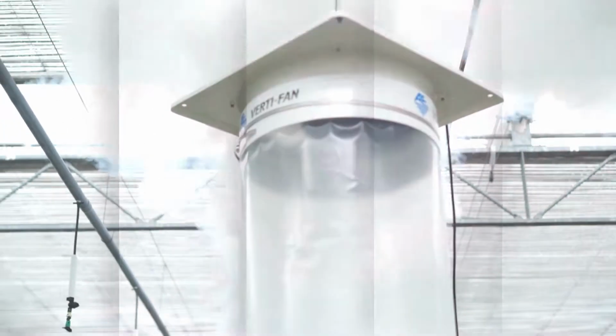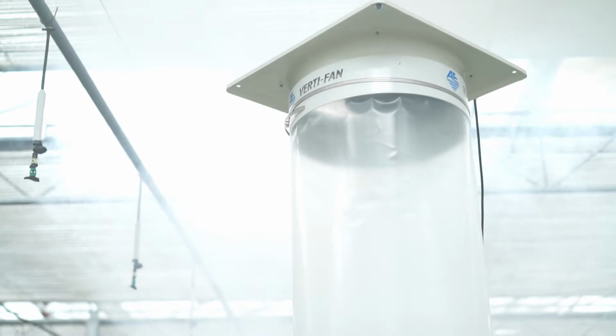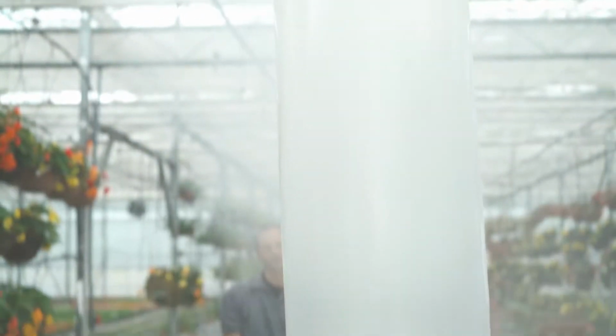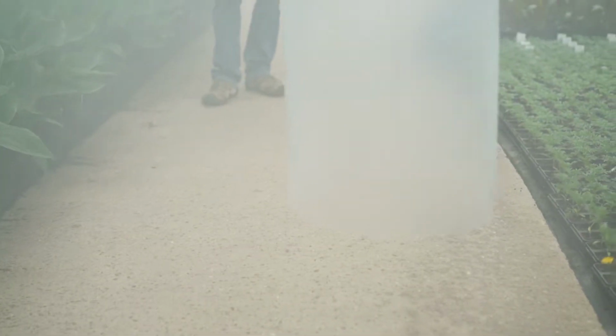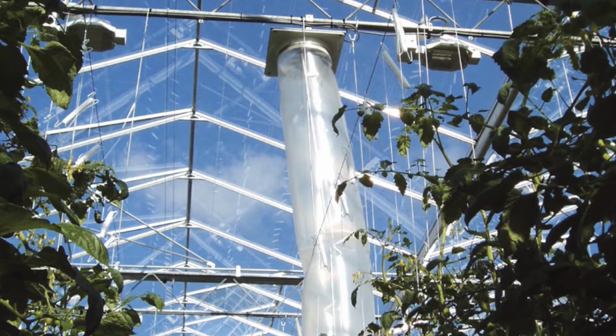Instead of moving air across the greenhouse horizontally, which can result in layers of air moving at different speeds, a vertical setup can be a better option for making sure air penetrates the crop. In addition, air is moved a shorter distance, meaning a lower power fan can usually be used.